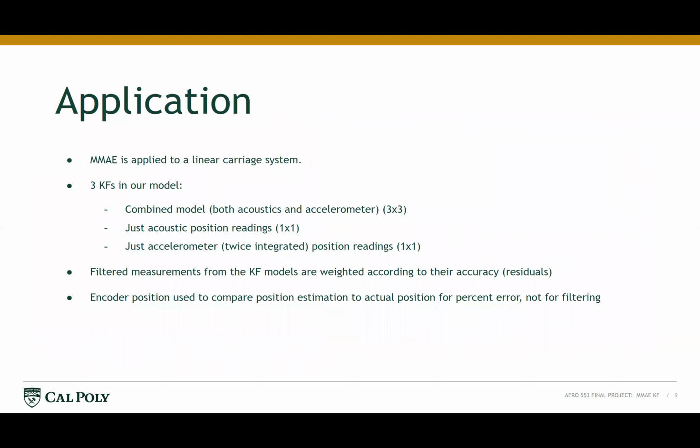In order to make the data collection and position estimation better, we are applying the MMAE model. We have three Kalman filters in our system. First is the combined model, which combines both the acoustic position and the accelerometer acceleration readings. That's a 3x3 system, and that was the system that we showed in the very beginning.